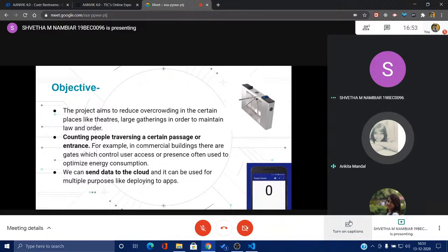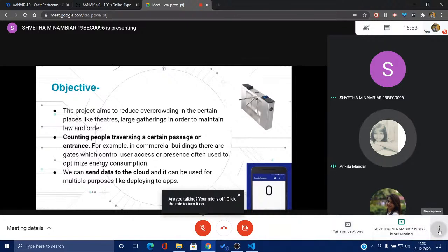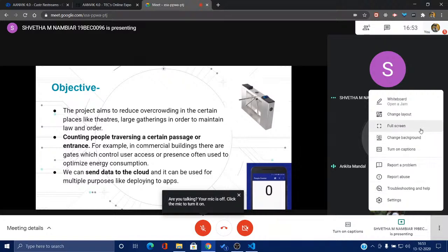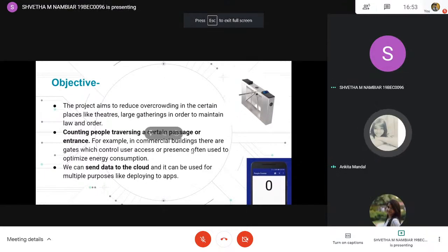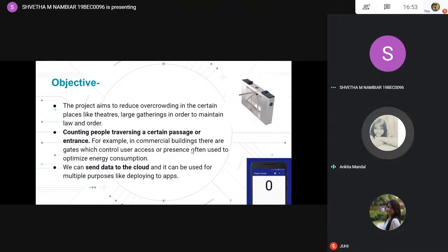Some other things you can do is create a smart thermostat using IR sensors that can perform motion and presence controlled operations to, let's say, save energy. But one application that closely relates to our project would be the use of IR sensors in the assembly line of a glass factory, where you can use the sensor to count the number of objects being produced or the rate of production. And here also we are doing object detection, the object being us humans.